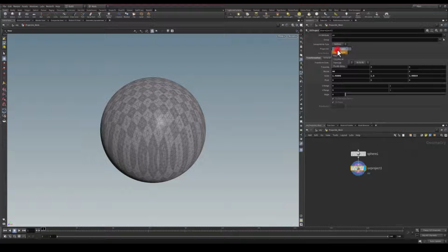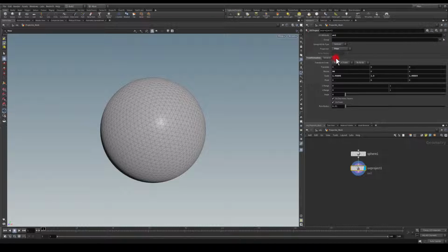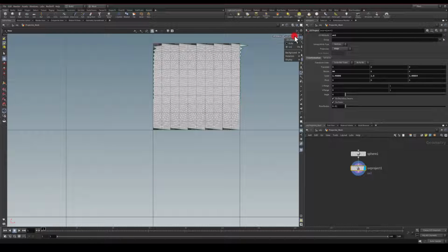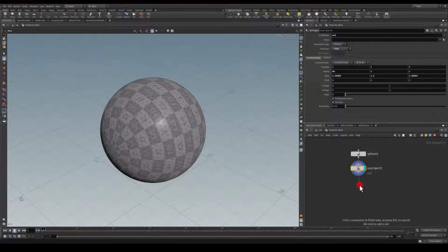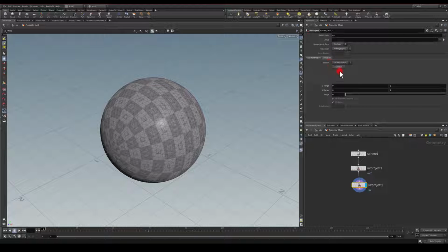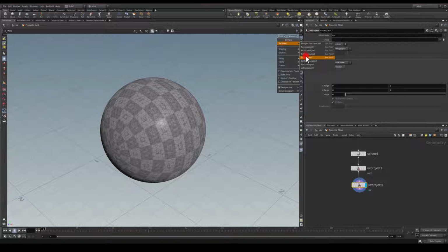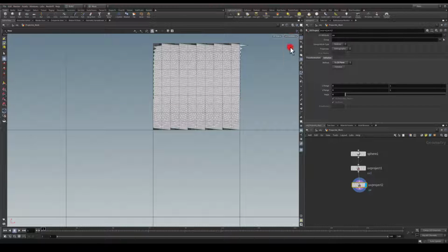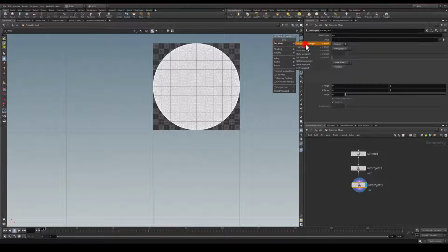For this one I want my UVs to actually be on the UV channel 2, and I'm gonna change them to be polar. I'm just gonna dive into UV editor, make sure it's correct. So it looks okay. I'm just gonna get back to perspective and get another UV project. And this one's going to be orthographic because I need a side projection. I'm gonna pick Z and X plane and initialize again. Dive into UV editor just to make sure it looks okay, and it does.